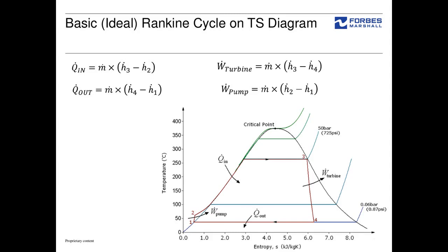So the boiler acts as a heat source where you burn fuel or recover waste heat, and heat is taken into the process, which is used to change the phase of water to steam. There is a heat sink in the condenser, so from process 4 to process 1 heat is rejected to this cooling media or atmosphere. Okay. Work output is taken from the turbine and work input is given at the pump.